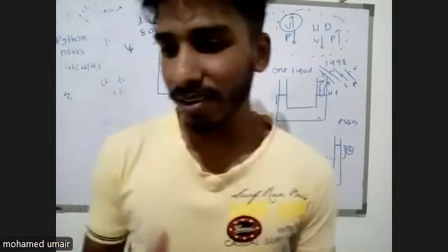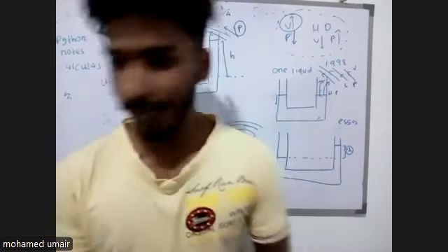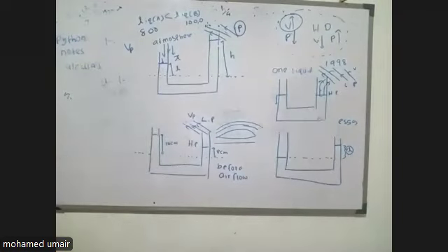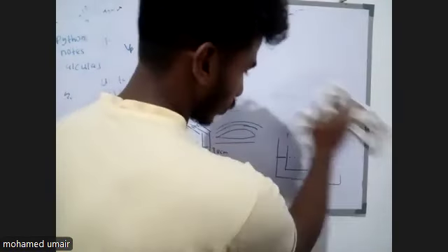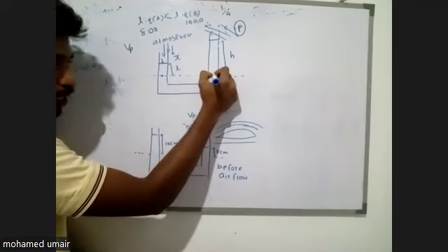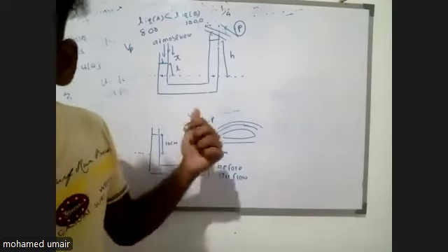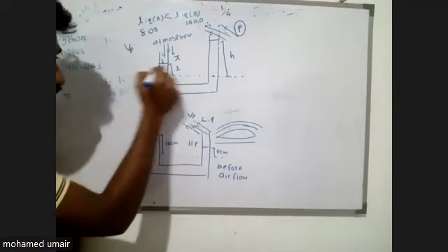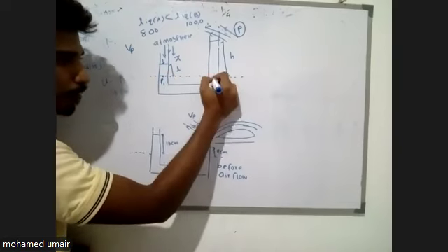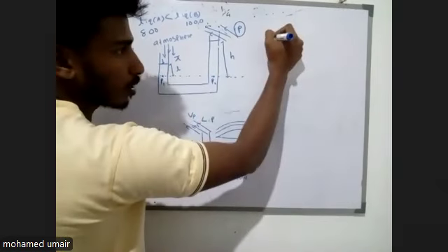So now let's start our basic equation. As we have studied in the U-tube, just try your basic equation. So I'm erasing these parts. If I write the equation for the pressures at these two locations, they are the same liquid. Sorry, it's the common interface. So the pressures at these two locations are the same: P1 is equal to P2.